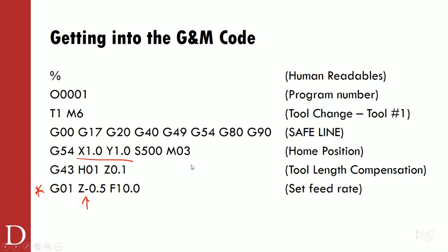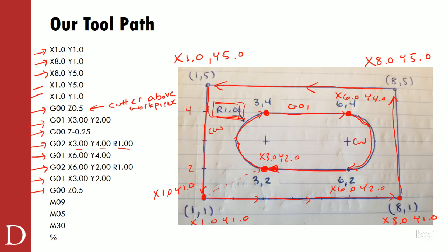One thing to note, you might have noticed this down here. In the NC simulator, you can put as many M codes on a line as you want. I will tell you that's going to cause you grief when you go to download to the Haas machine. It only allows 1 M code per line, so be careful. So I'm turning the coolant off. Should have turned it on before. Here, I turned it on up here. How's this? M08. Coolant was on.